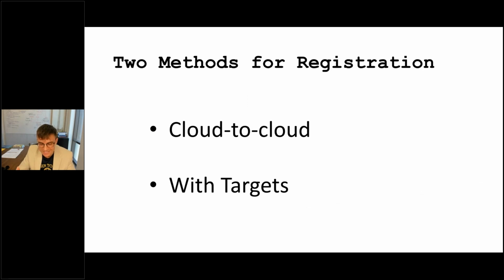Sometimes using targets can be inconvenient though. For example, clean rooms are very controlled environments, and so you want to minimize the amount of stuff you bring into them. High traffic areas make targets insecure, and so that kind of defeats the point of them. Sometimes you just don't have time to set up targets, and you have no choice but to do cloud to cloud in these cases.